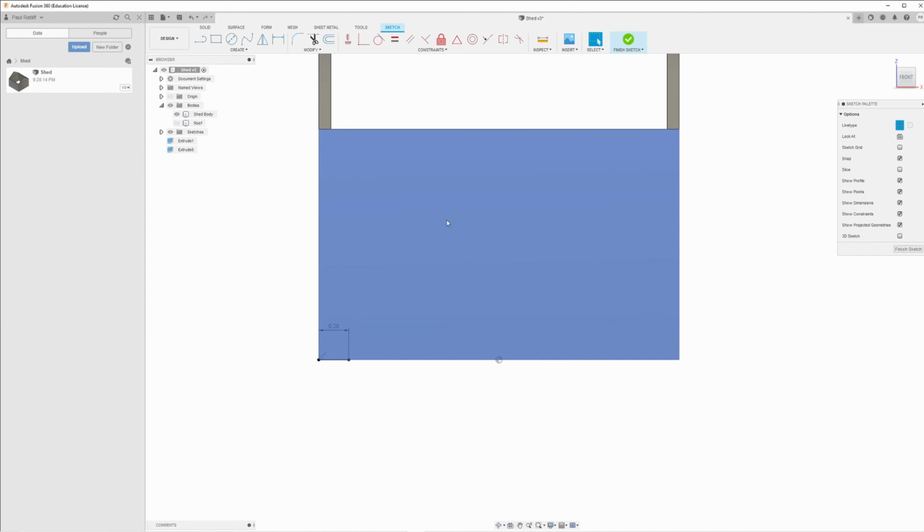So we've got this selected. Go up here and get our rectangle again. Start on this point. Start dragging. Now, it's doing the width first. You see the width is highlighted, so 0.7. That's our width. Go up here, tab it, and do 1.3 for our height. And that created a stray construction line, which I don't want.